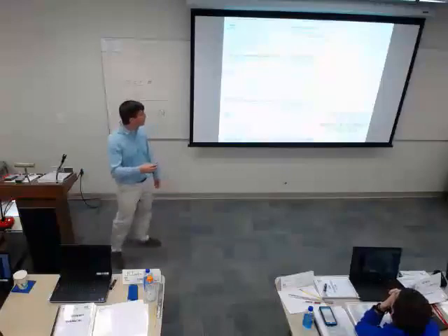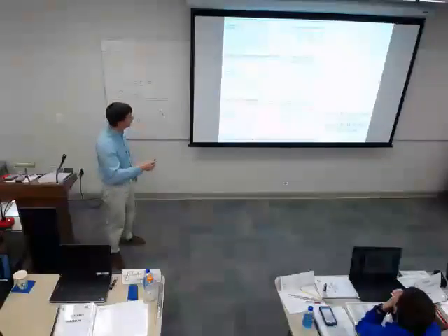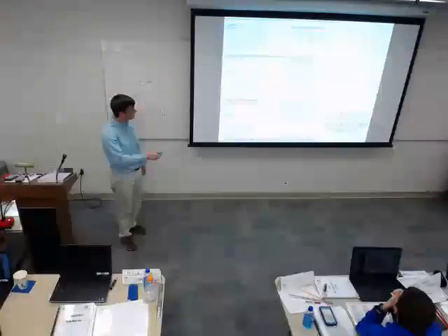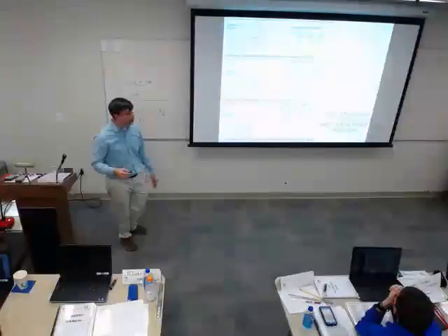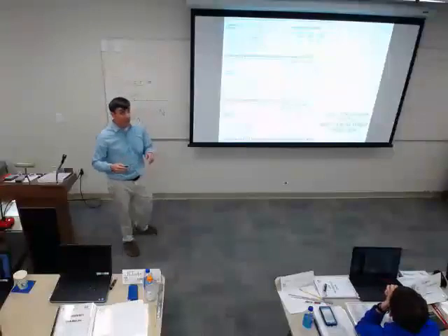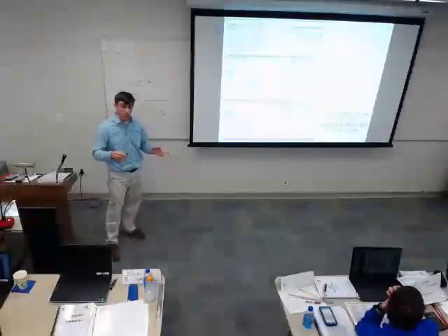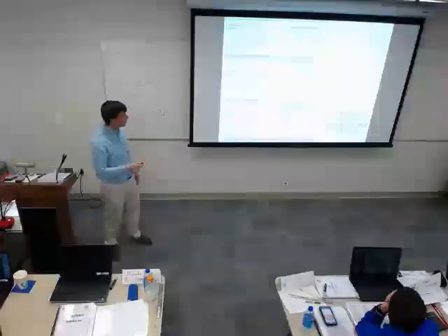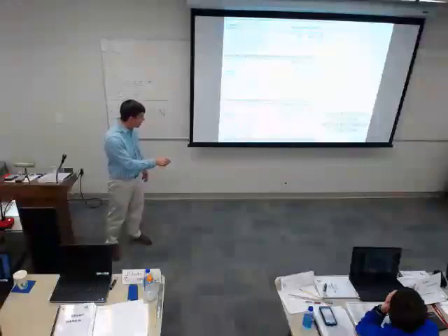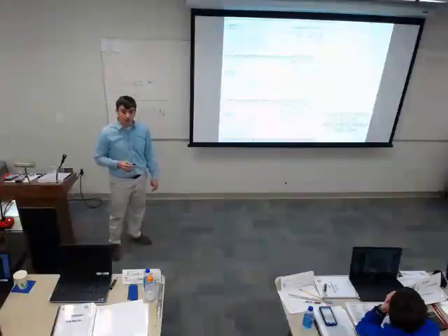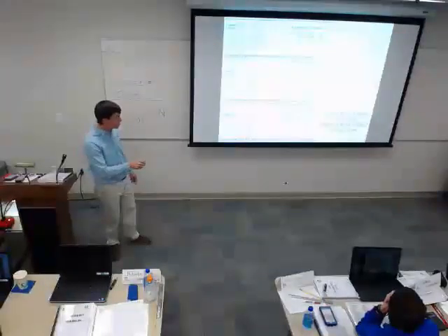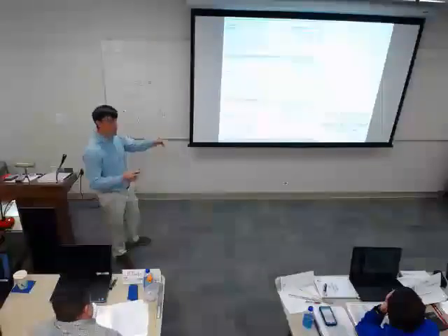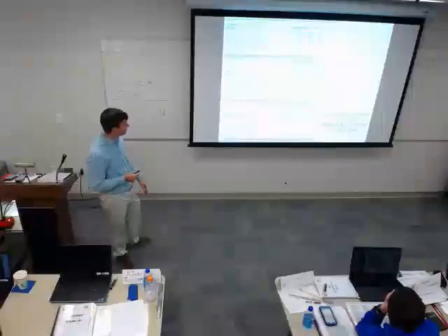It also matters on the inlet. This is basically the same situation here. The point of all this is that the type of elbow on your inlet matters. Not only does the distance matter, but the type of elbow matters as well. So remember that the lower the letter, the more resistance. A square elbow is in the N to S range, and a radius elbow is in the S to W range. So these are less resistive, so they give you less system effect. They give you better flow conditions coming into your fan.